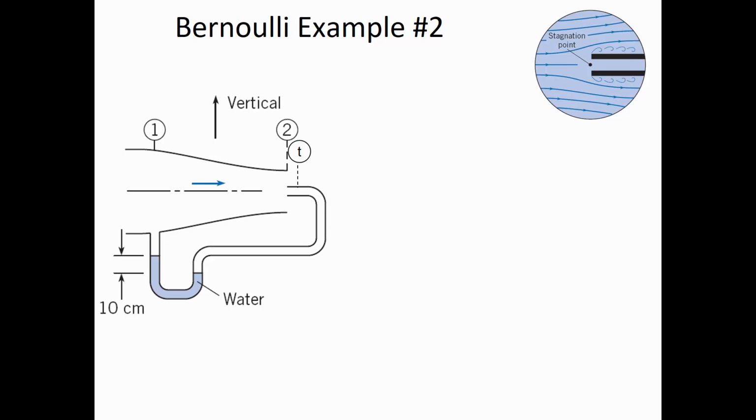if we were connecting at this spot, then the pressure wouldn't be quite as high as when you've got the tube pointed like this. Because if the wind is going past the opening, it's just going to be measuring the ambient pressure.